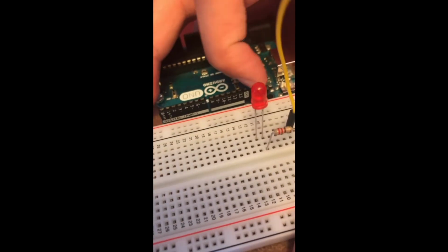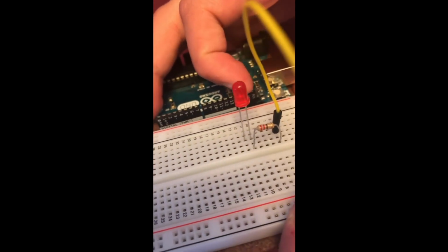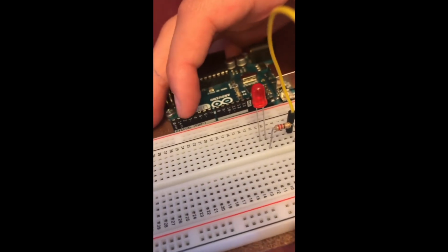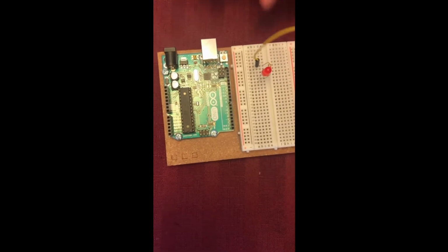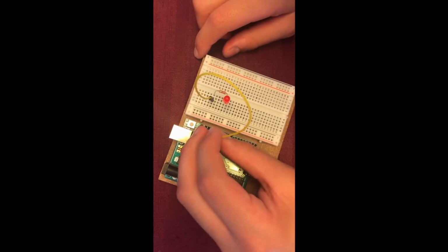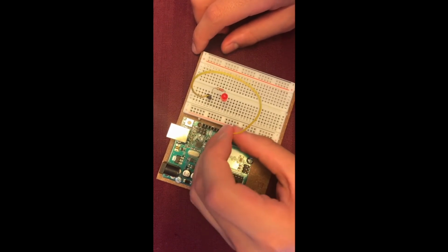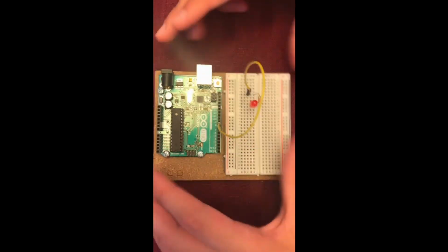to one of these pins, but not the ground, AREF, SDA, or SCL. Just these pins, so 0, no, not 0, sorry. 2 to 13. These ones you can use. Or 2 to 12, I'm not sure. 2 to 13, I think, yeah. So I'll just connect it to 8. You can connect it to whatever you want. Make sure it's 2 to 13.